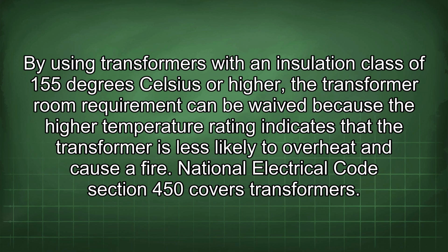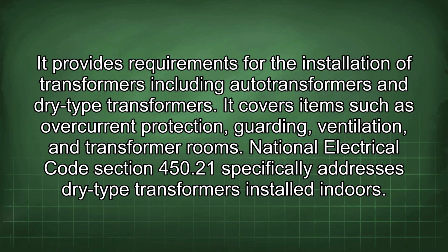National Electrical Code section 450 covers transformers. It provides requirements for the installation of transformers including autotransformers and dry-type transformers. It covers items such as overcurrent protection, guarding, ventilation, and transformer rooms. National Electrical Code section 450.21 specifically addresses dry-type transformers installed indoors.